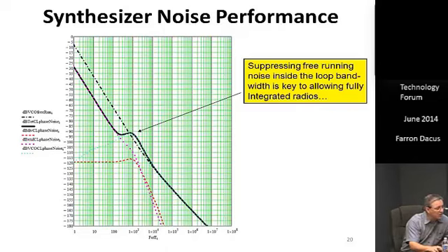As we get into loop bandwidth, it starts suppressing that phase noise. Now, in a lot of modern integrated synthesizers, you have pretty poor Q on the die, and you get poor phase noise as a consequence, because according to Leeson's equation, phase noise goes down with Q squared. And with this lousy Q, integrated VCOs are typically noisy,